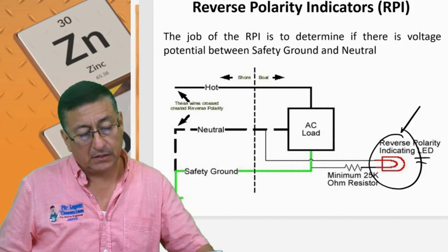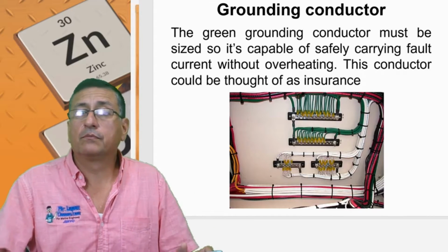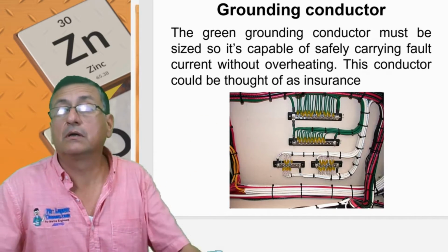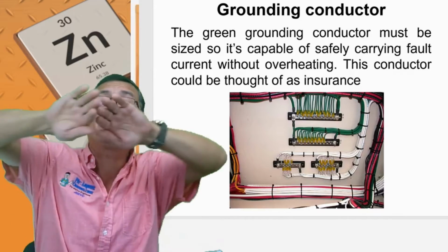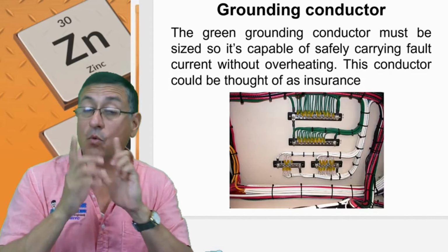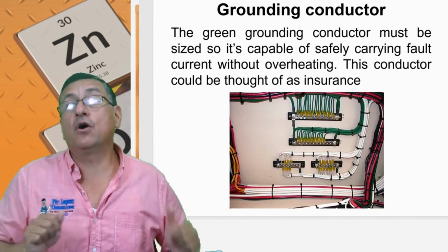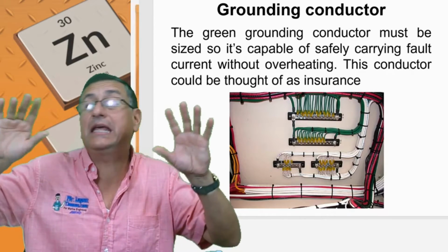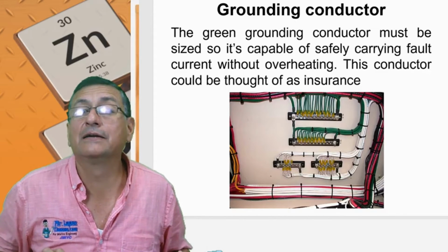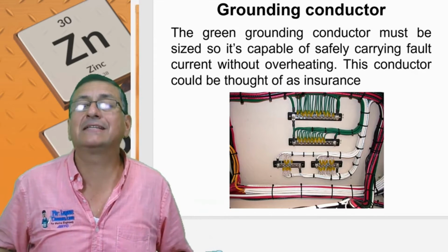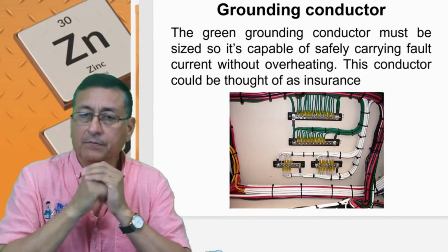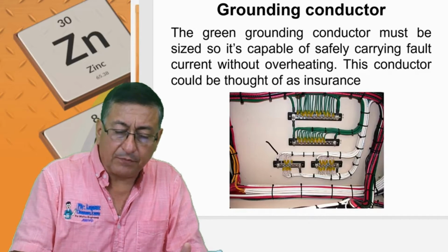Okay, let me explain what happens. This is the situation. Normally in the wiring in your boat, you have a ground bus bar, the green bus bars, and neutral bus bar, the bottom ones, white color. Those bus bars are independent. Those bus bars should be completely separated, individual, independent. Why? Because if you have one of those, the neutral, with power, and suddenly some non-marine electrician puts together the neutral and the ground bus bar, kaboom. This is catastrophic for your boat. Why? It's simple. Suppose that you have reverse polarity. In this moment, you have power in this bus bar. You have power in the neutral.